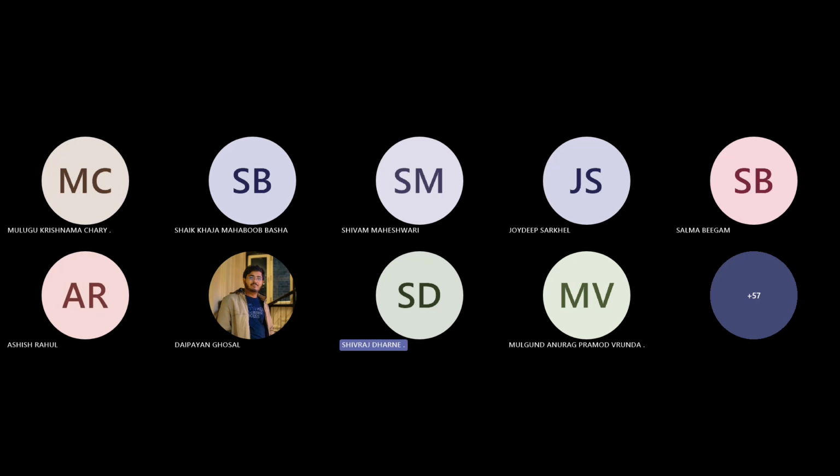Second, you can give some example names, these are the places I will check. And then tier classification, exactly Uptime Institute tier 1 to tier 4, right? Tier 3 means concurrently maintainable. Because of the cost versus uptime trade-off, right? Why you went for tier 1, tier 2, tier 3, tier 4? What tier 1 means, tier 2 means, tier 4 means, and why you went for tier 3? Tier 3 means concurrently maintainable, and this is because you are trying to do the cost versus uptime trade-off and you have selected. Then you will say, I will go for electrical design, right?